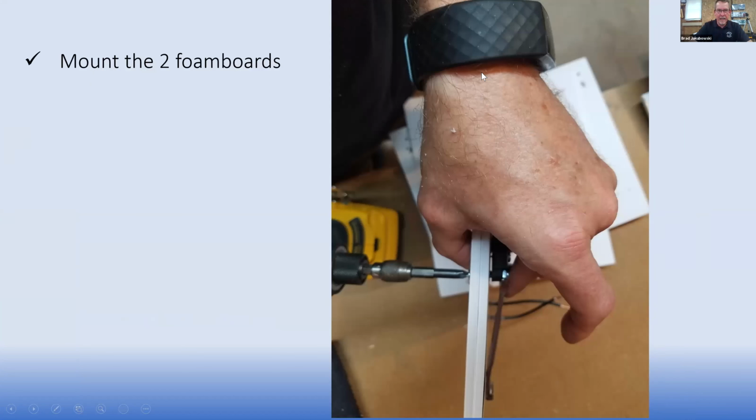Once I got that done, and you get those things trimmed out, if you wanted to do that, the next thing would be to mount the terminal strips. That's a matter of just pressing these in. Fortunately, there are little metal posts on the back of these terminal strips, and they'll pop into that. So they actually hold this terminal strip in place.